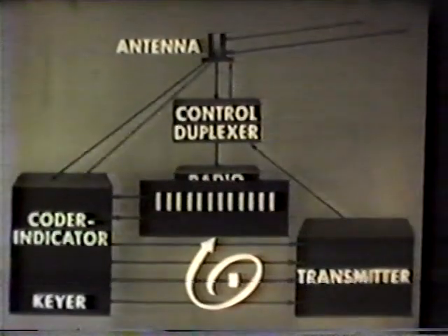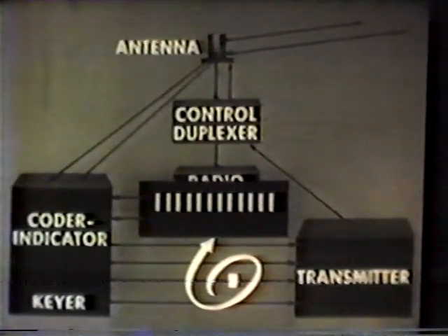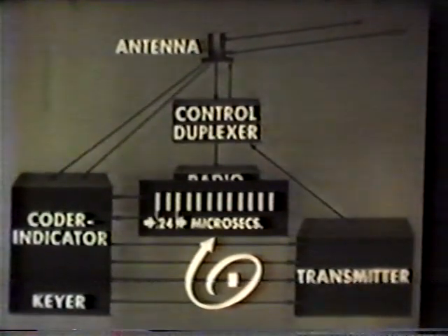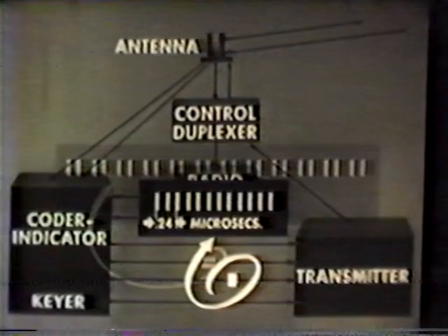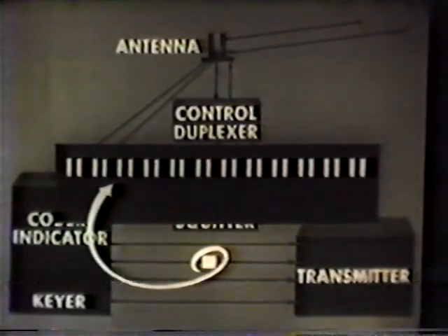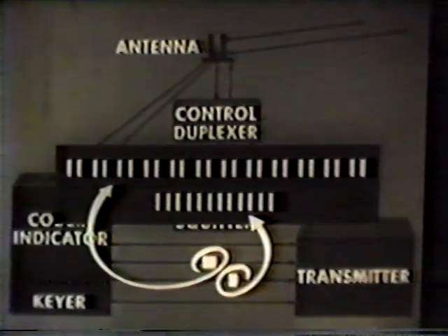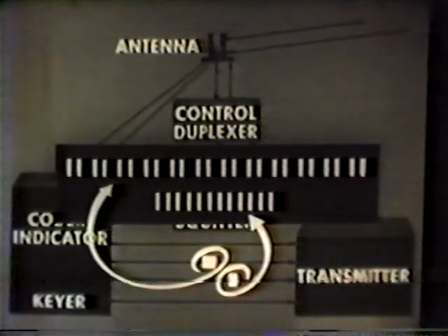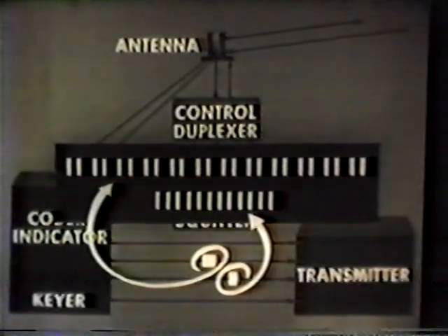The auxiliary reference burst train consists of 6 pulse pairs spaced 24 microseconds apart. The number and spacing of the fundamental burst pulse pairs are different from those of the auxiliary bursts, so that the aircraft's equipment may distinguish one type of reference burst from the other.